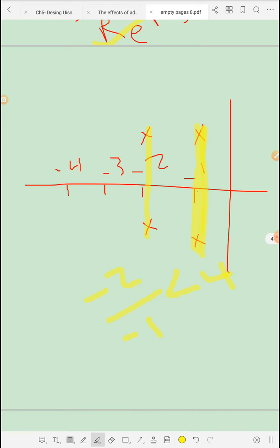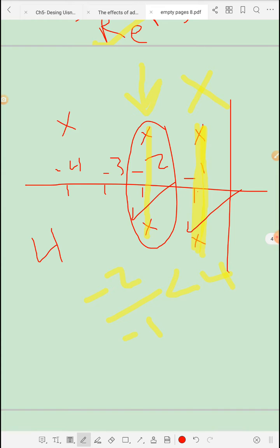So this means that these are not dominant closed loop poles, because those closed loop poles are close to them. The relative distance of the dominant closed loop pole to the non-dominant, as I previously mentioned, should be at least 4 times. So in order for those to be non-dominant, they should be placed around -4, so -4 over -1 equals 4.